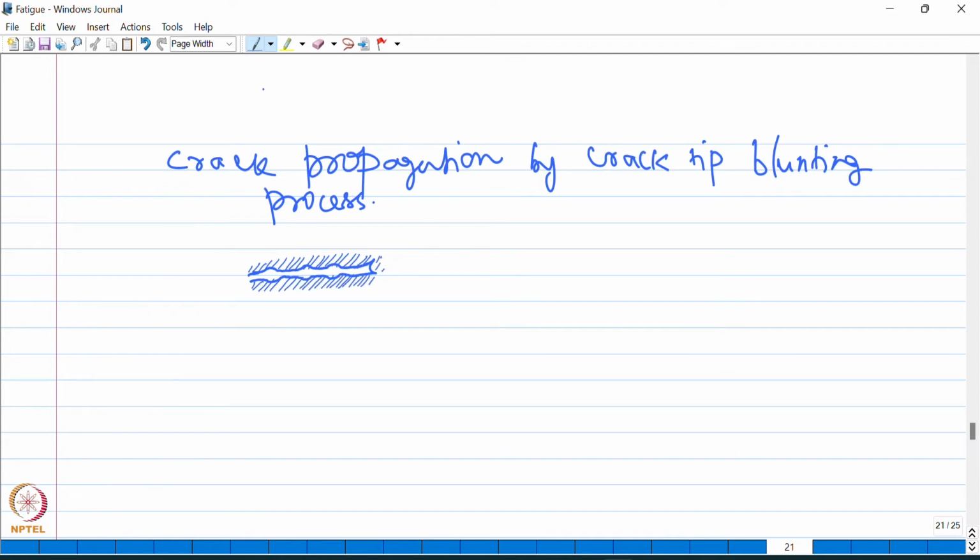And as the tensile load is applied, the small double notch that you have at the crack tip concentrates the slip along planes at 45° to the plane of the crack. That can be seen in the second diagram here.